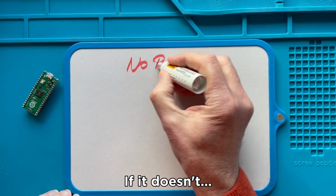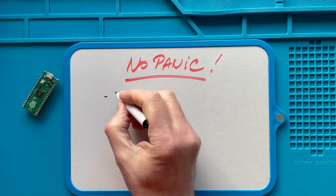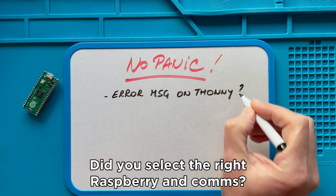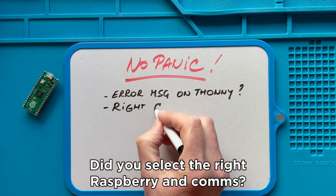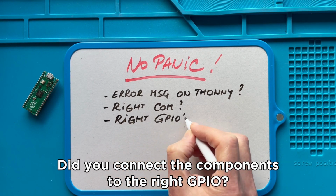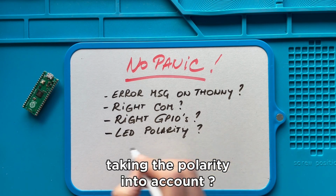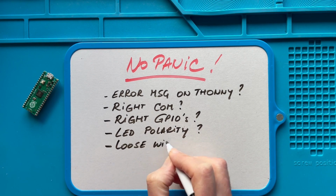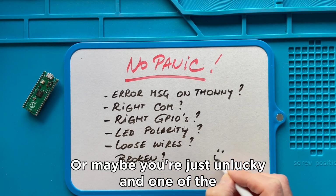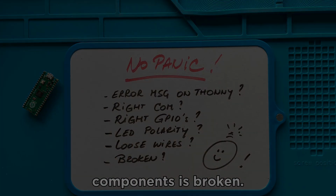If it doesn't, no panic. You can do some logical fault finding. Were there any error messages in the REPL or in Thonny? Did you select the right Raspberry and comms? Did you connect the components to the right GPIOs? Has the LED been mounted correctly, taking the polarity into account? Were there any loose wires or legs? Or maybe you're just unlucky and one of the components is broken.